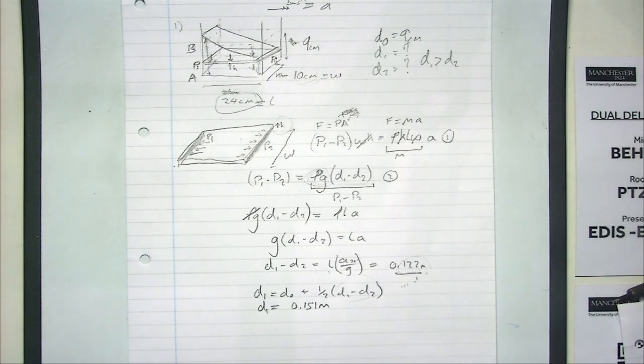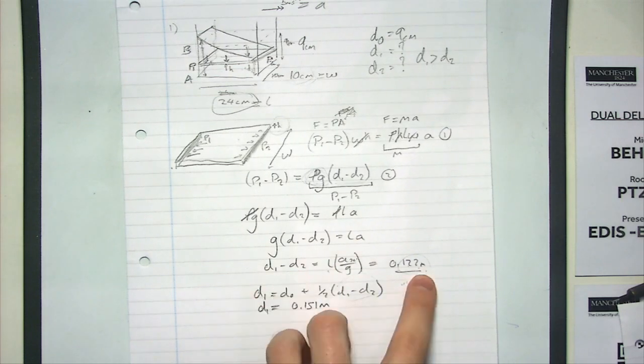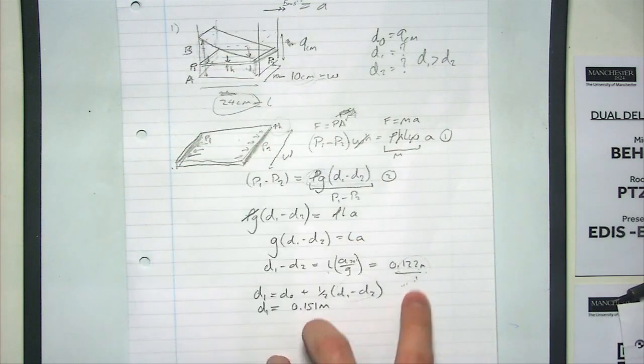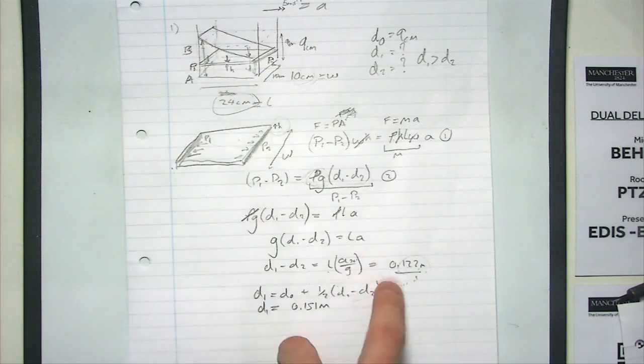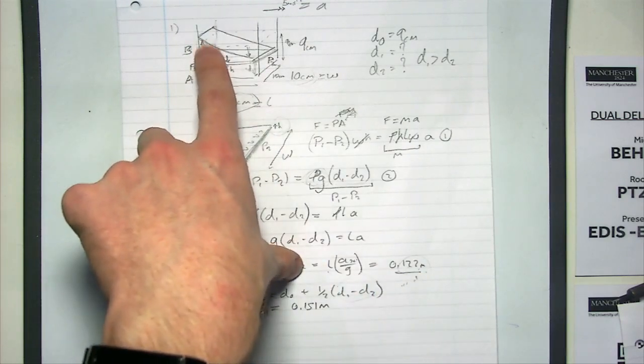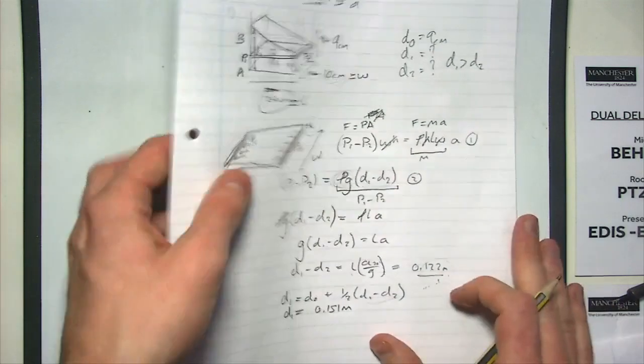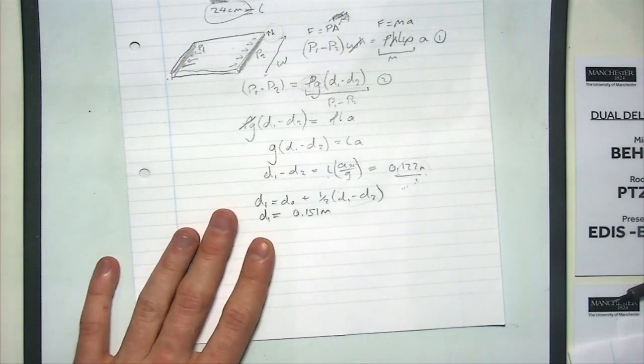So the water is at a level, and it shifts as it accelerates, right? That's intuitive to you, yeah? When it shifts, the amount it rises up is equal to the amount it rises down, right? So the difference that we found, this value here, is double one of these rises, right? Is that clear? So we're saying that half of that distance, half of that difference in depth, is what gets added to this here. Are we okay with that? Okay. So that's how we find the depth of the bit on AB.